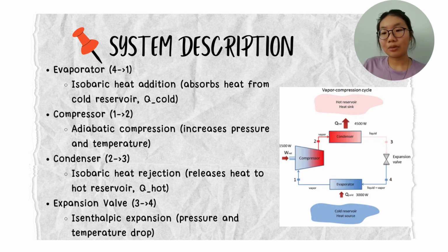And last but not least, our expansion valve. The expansion valve is from stage 3 to stage 4, and it is in an isenthalpic expansion condition, which means H4 is equal to H3. The pressure and the temperature in the expansion valve will drop.